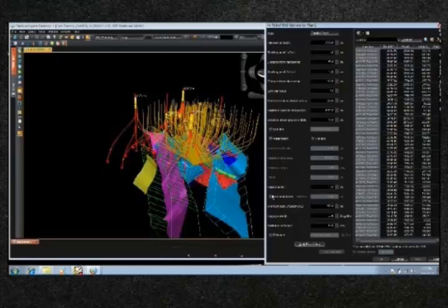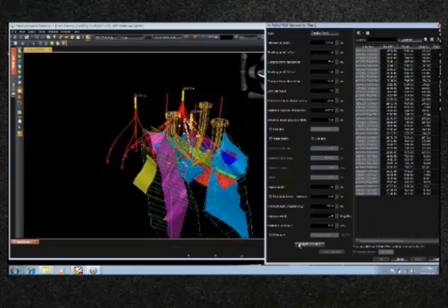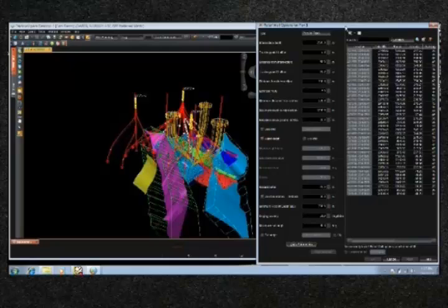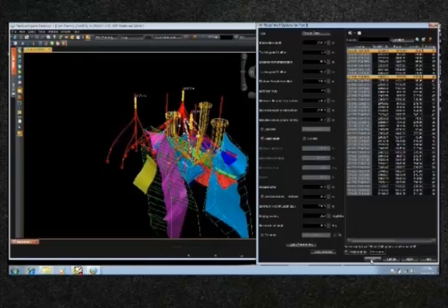We can then tell the application to now narrow down that list of relief well plans to those that originate only from those three areas. Once we apply those parameters, this list is then narrowed down for us, and we can visualize what it has done in the 3D view as well. We can then sort out these relief well plans according to the parameter of importance, just as we had done in the sidetrack planning. And once we have selected the plans that meet our needs and criteria, we simply give them unique names and create those plans.